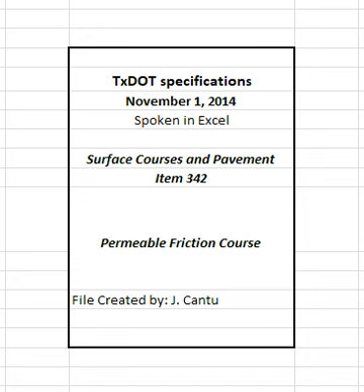4.4.2.2.10 Binder content adjustments. For JMF2 and above, the engineer may require the contractor to adjust the target binder content by no more than 0.3% from the current JMF. 4.5 Production operations. Perform a new trial batch when the plant or plant location is changed. Perform QC at the frequency and within the tolerances listed in Table 5.